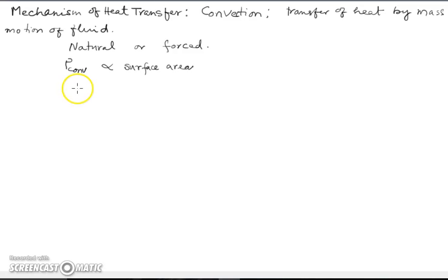Second thing is that the viscosity of fluids slows down natural convection near a stationary surface, giving a surface film. Forced convection decreases the thickness of this film, increasing the rate of heat transfer. And this is the reason for the wind chill factor.